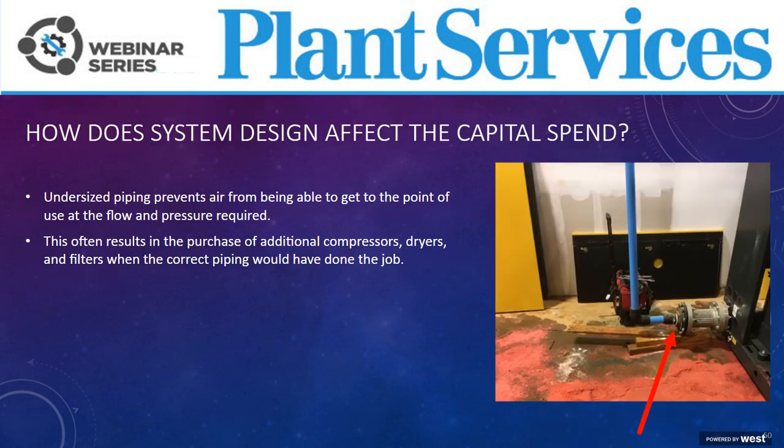Another thing that affects capital spend is using the wrong pipe size. Again, Neil touched on that subject, and here's a nice example of going from about a 3-inch pipe down to a 1.5-inch pipe to go into the distribution system. What happens in cases like this is you wind up with low pressure in various parts of the plant, and a lot of times the solution to having low pressure in a distant part of the plant is to buy another compressor and locate it near the area of low pressure, when in fact, a compressor was not what you needed. What you needed to do was correctly size the pipe.